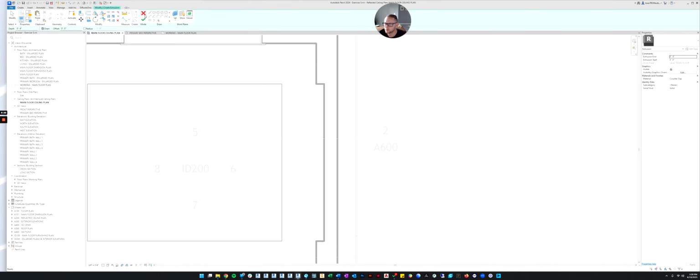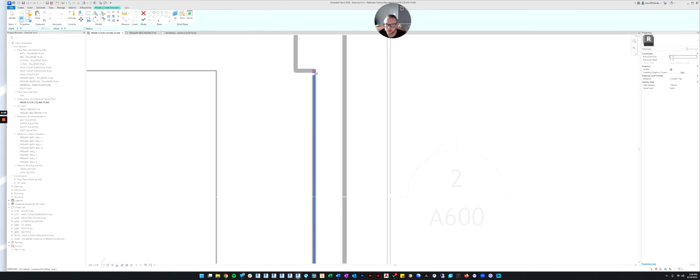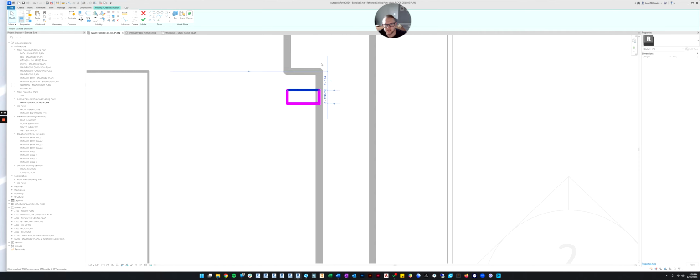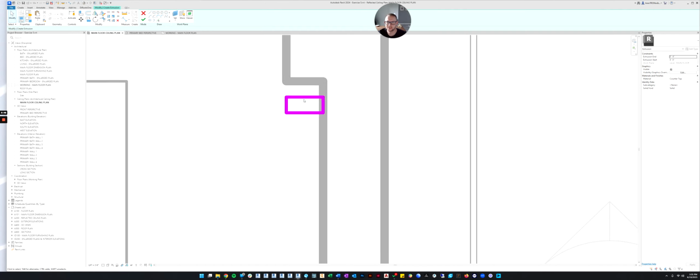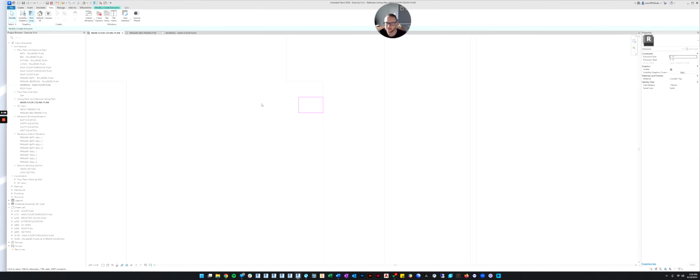And now, if you watched the last video, you know how to do an extrusion. So we'll hit extrusion. We're just going to draw a rectangle like this. And let's drag it so that it is 2 inches away from the wall. We can keep it 4.5 inches deep, and let's make it 2 inches wide, like that. So now we've got a slat. Maybe we don't want it that deep. Maybe we want it 3 inches deep. And I'm going to go to the View tab and shut off my thick lines because I don't like that.